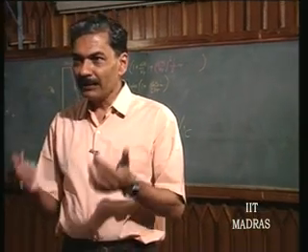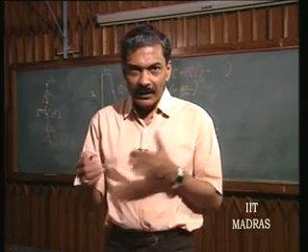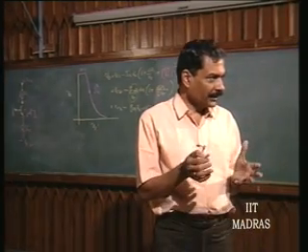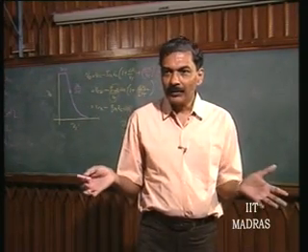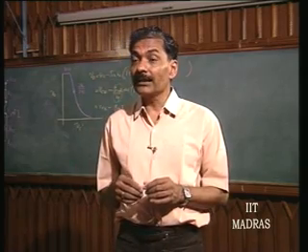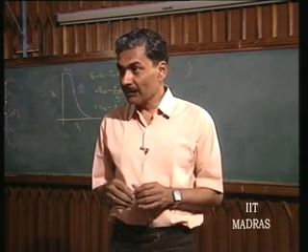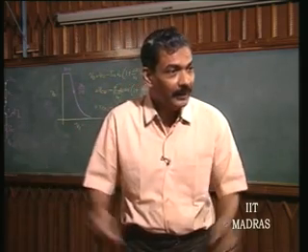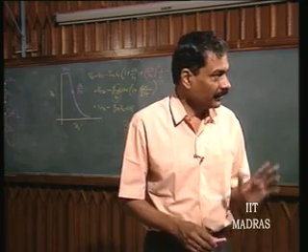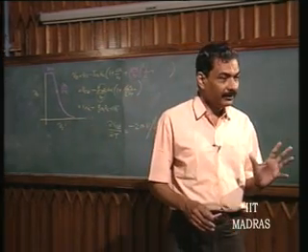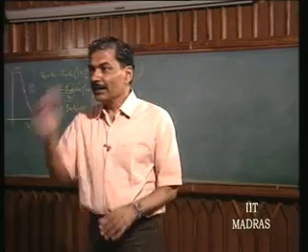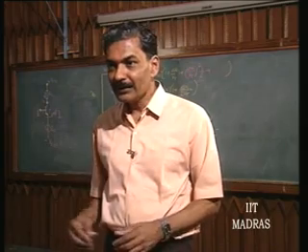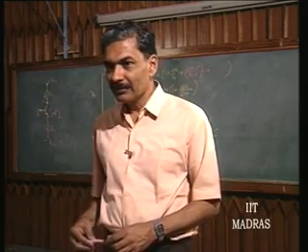So, that principle that we depend upon so much in integrated circuits, that when the transistors are equal, okay, and if the base emitters are at the same potential, then the current should be equal, is what is used for biasing it in a stable fashion. That means the biasing is not going to be disturbed, it is going to be I naught by 2. I am able to tell without any hesitation. That means it is a stable biasing. And apart from that, what have I achieved? As far as the signal is concerned, it is going to act as a near short, not exactly a short. What is the impedance from that emitter to ground?